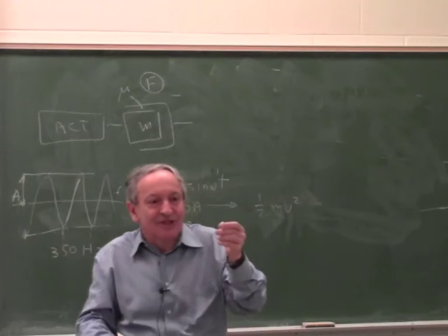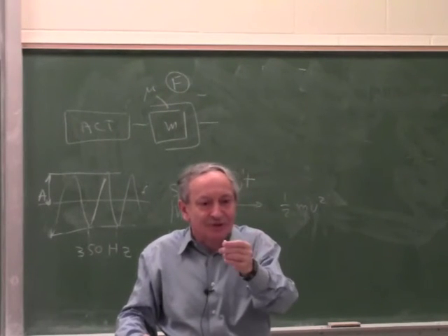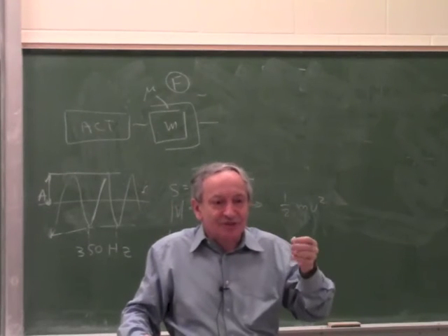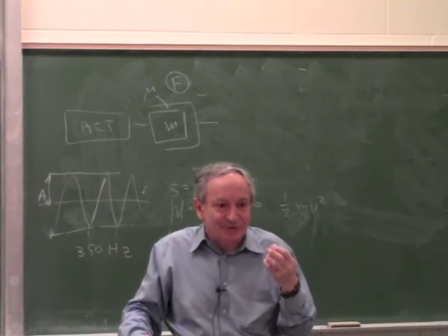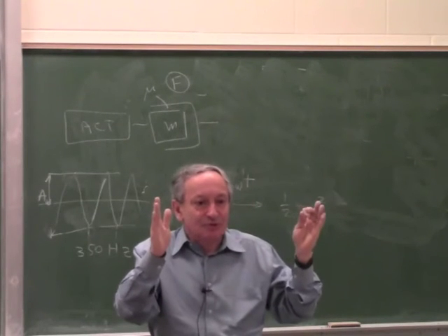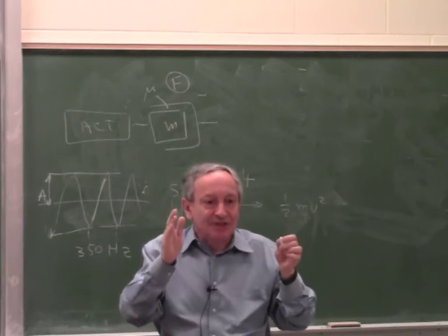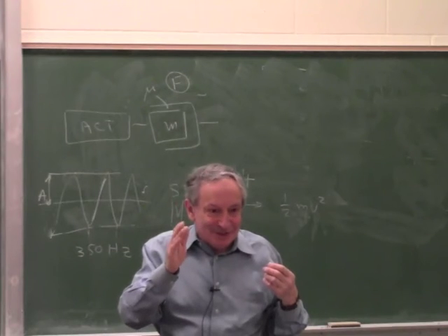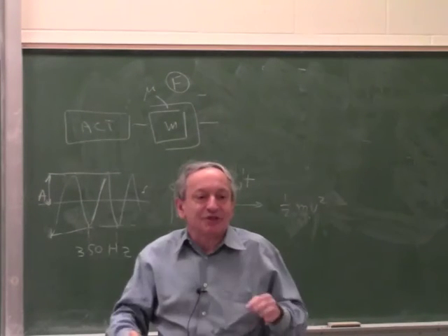It doesn't matter if it's not a sine wave. I have a mass and I move it fast, and I move it slow. But eventually, any acceleration I put into it is stored as kinetic energy. Eventually, this kinetic energy has to come back out, because I have to brake it, because it's constrained. The total position is constrained between two points. So every bit of acceleration I put in, which became kinetic energy, is still there, and I can get it back out. It doesn't have to be a sine wave. Think of an electric car which has no losses.